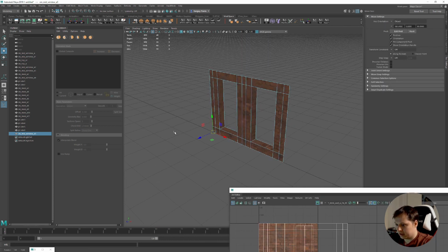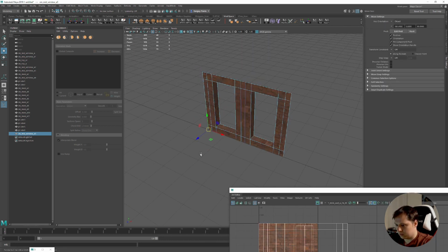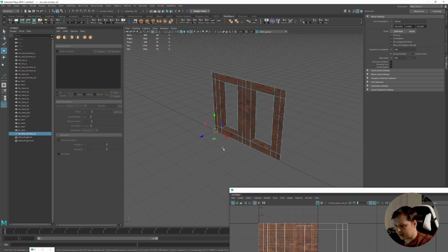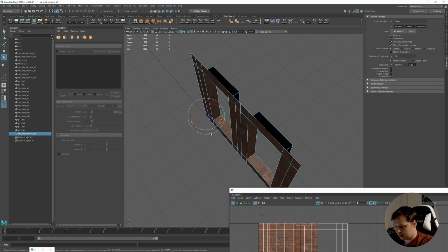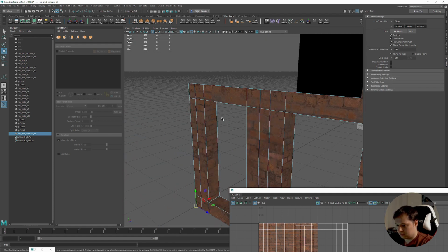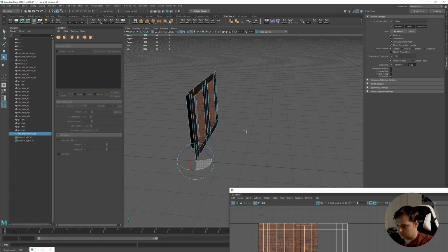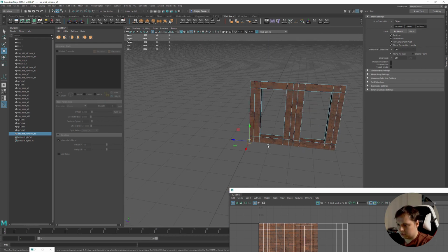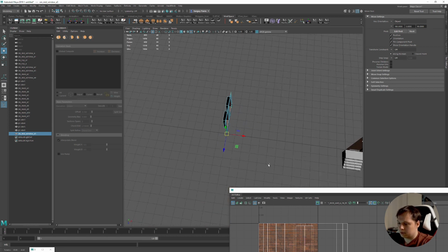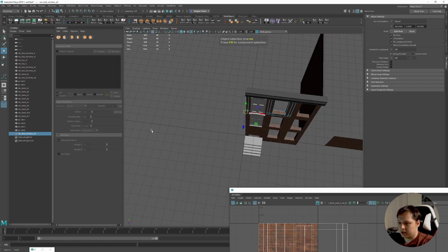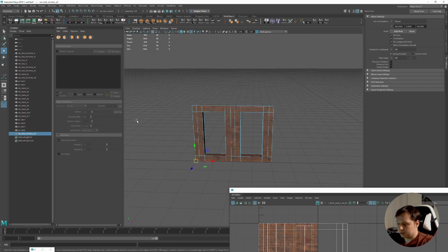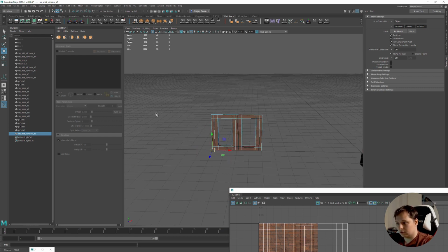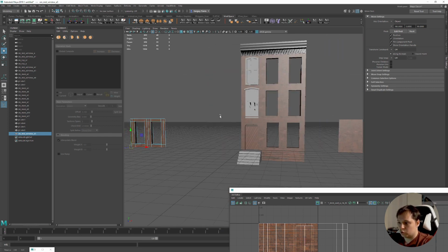One important thing, do not forget, is the proper orientation of the mesh. If you're working on modularity, remember that everything should be looking the same way. In our case, Z is front, X is right, and Y is looking up. But in some studios, it can be something different, right? It's important to remember because otherwise you will need to rotate the module in engine by yourself, and it's not very comfortable. And as we talked about at the start of the video, the most important thing in modularity is that it should be comfortable for everyone.